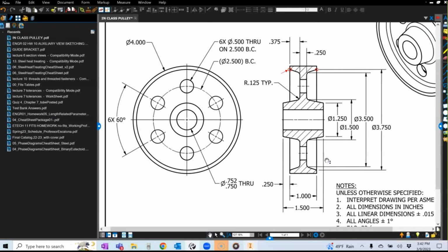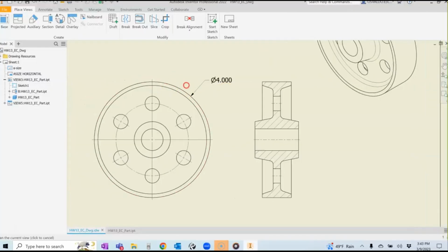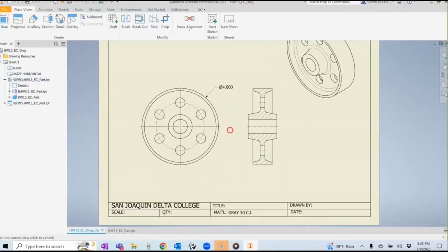Let's see, what do I got? I have a couple of callouts here. Say you got 6 of them, diameter through on a 2.5 bolt circle. When you have a cylindrical part that you need to dimension, you do not dimension with a datum plane, because there is no datum, right? The datum that you use is an axis datum. It's not a plane datum. In other words, you go from the axis and move out from the axis. So if I want to move out from the center of the axis towards the outside, what would I see?